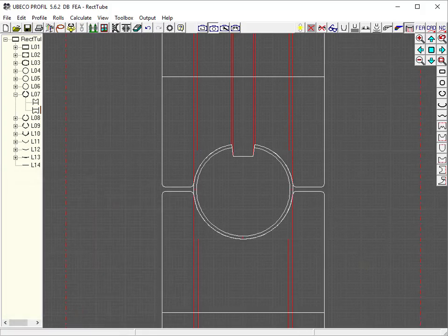For example, a 1.5 millimeter wall by 78 millimeter OD medium strength steel tube flange gap could be 1.25 times the wall thickness, or 2.25 millimeter without extruding material into the gap. The flange gap provides the machine operator adjustment capability to accommodate wear in the roll tool root diameter, or in an increase in material yield strength where additional compression of the section is needed to create the desired dimension when the section exits the driven stands.